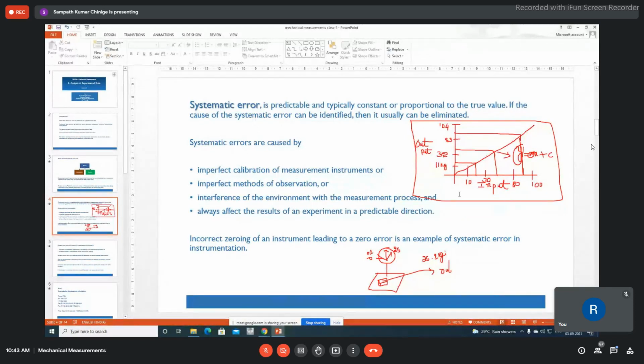So for that, what I am doing is a process which we call calibration, where I know the input values, which are standard. I am very sure of the input values I am giving. There is no error. Even if an error is there, it's a very minute error. So we always have to perform the calibration with the help of known, precise or accurate input values. So now I am very sure about the 10 kg, 30 kg, 80 kg, 100 kg. They are very, very accurate, precise.